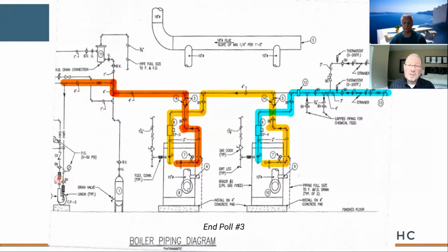The only time you'd want to do this is if these are truly lead lag, meaning that only one boiler is going to fire at a time.